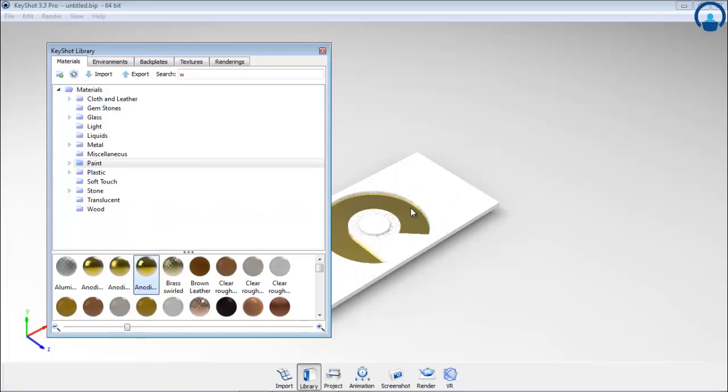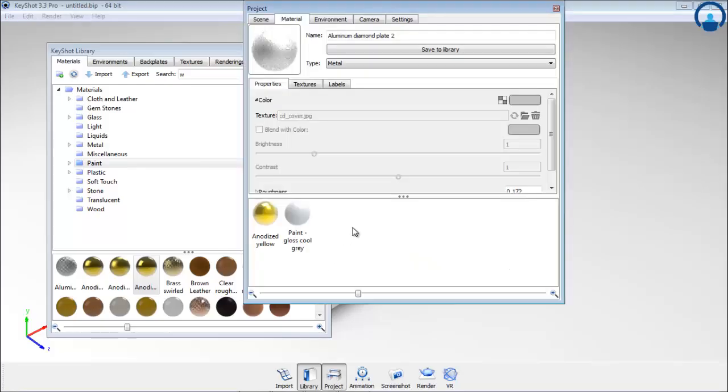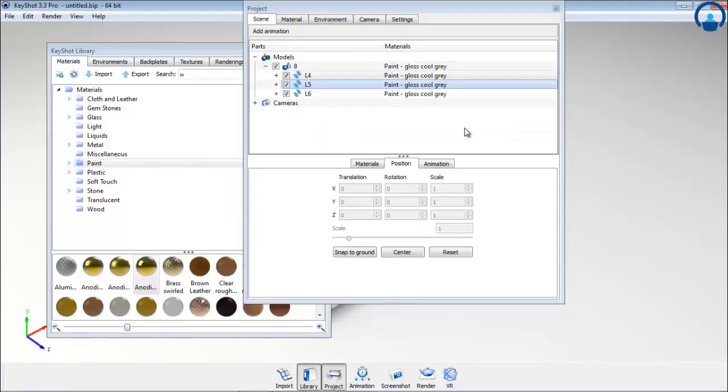To copy, paste and link one material to other and different parts, press shift plus left click to copy and then shift and right click to paste on the selected part. Or you can select all the parts you want to assign the same material in the scene tree and select link materials. You can also apply materials by editing the pre-existing diffuse shader.